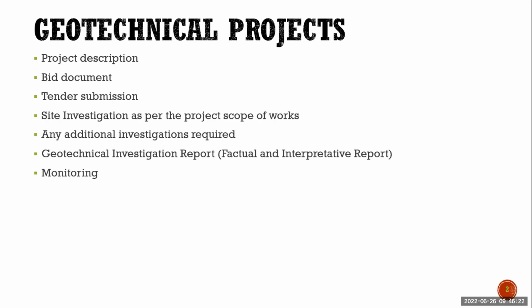Now, if it is exceeding that limit, immediately you have to reconsider with the geotechnical team what is happening in this particular zone. Like that, you have to monitor slope stability, whether any sliding is happening, or any change from what is given in the geotechnical report. And while we are doing the construction, what other new difficulties are you facing? You have to monitor whether everything is okay. So this is called monitoring.